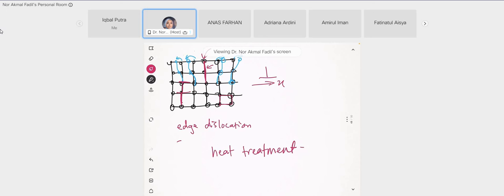So I remember last time, one giant company producing steel wire rope. Okay, steel wire rope. So the steel wire rope, before it becomes a rope, is just one single wire. Okay, the wire has gone through a drawing process. The drawing process is a kind of cold working process. So the original size is larger. When it passes through the dies, it will become smaller, but it is packed with dislocations, and it gives an effect of strain hardening.